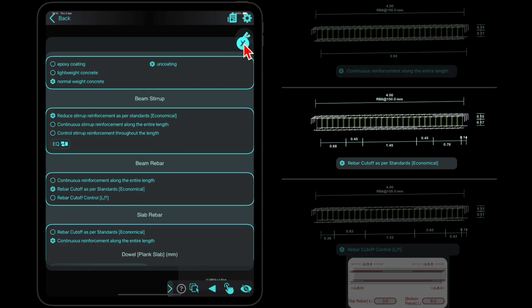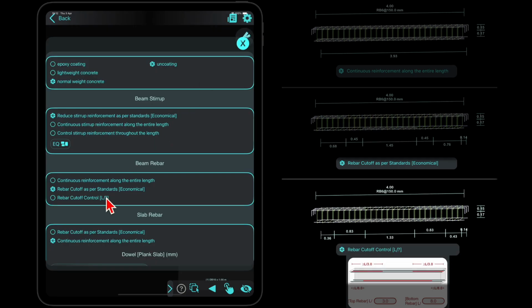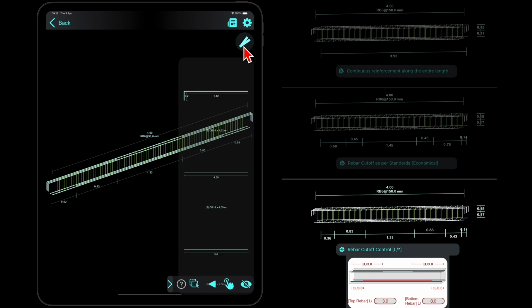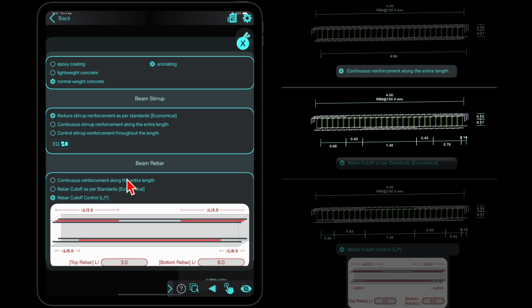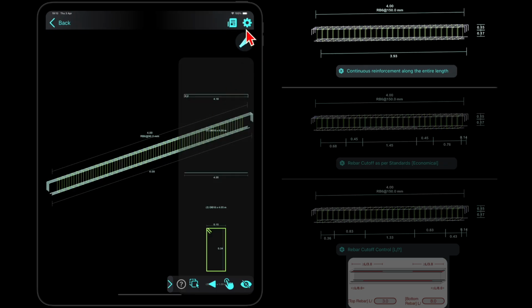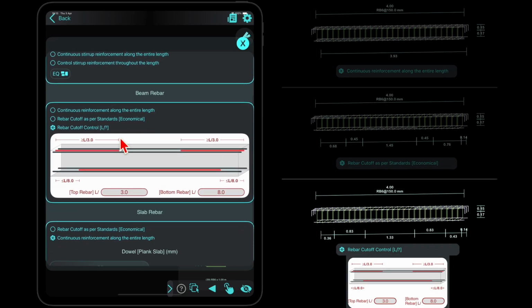Standard reinforcement detailing. This method calculates cutoff points using moment values, ensuring the shortest permissible bar length is used. This method controls bar length based on beam ratios and ensures safety by not allowing bars shorter than the standard full span reinforcement method. This method is recommended as it's both cost-effective and safe, in line with construction standards.